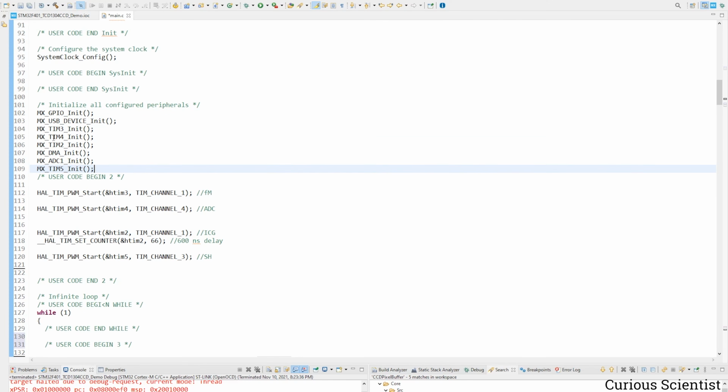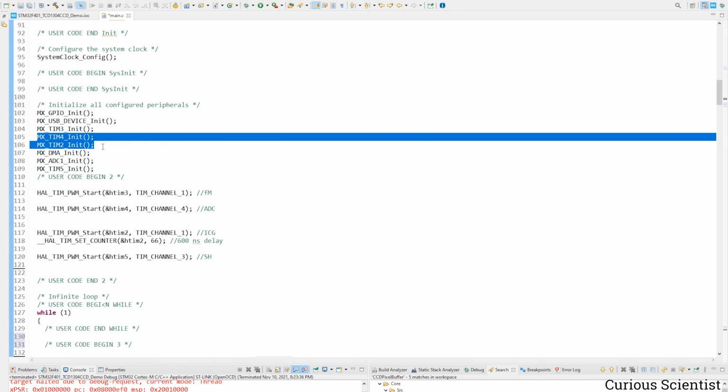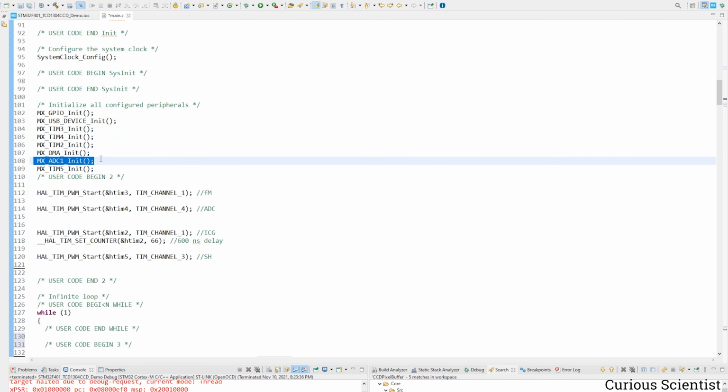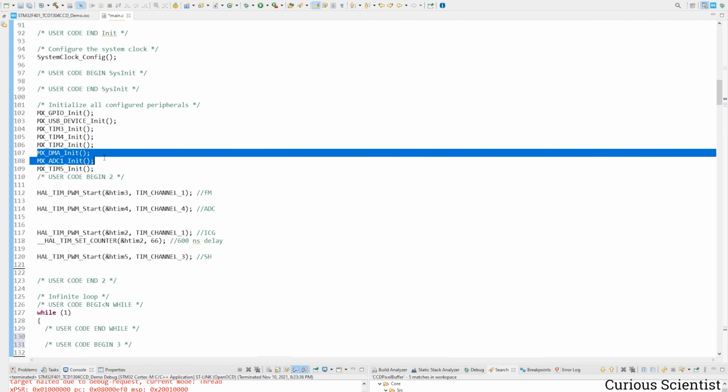And if you change something, it might happen that the order of these things changes in the wrong way, and the ADC is being initialized first, and then the DMA, and then you will not see anything in your buffer because it's not initialized properly. So always double check that first the DMA is initialized and then the ADC. So now I upload this code, and then I switch the ST-Link to USB connection, and we will see what happens on the serial terminal.